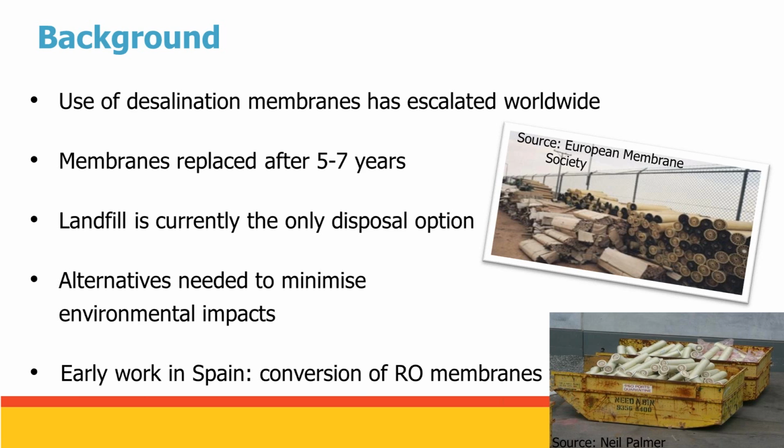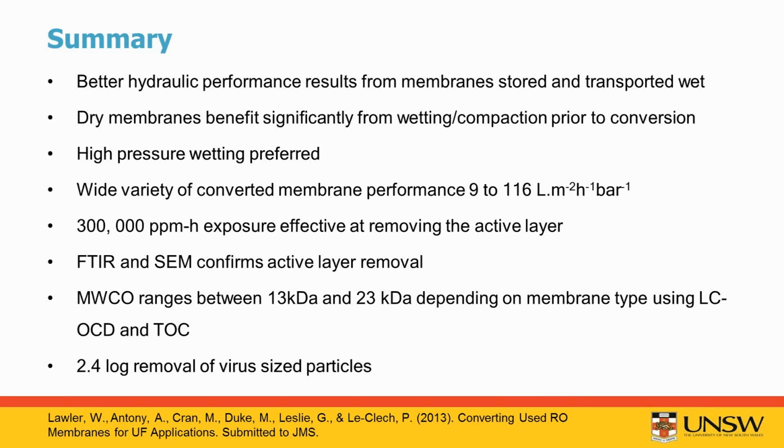And of course, now you're probably thinking, what sort of applications can we use this for? Using the test that we've shown, we say that we can use this potentially for pre-treatment for seawater RO, tertiary wastewater. Some of the more traditional applications for UF flat sheet membranes are a little bit outside the range, including pharmaceutical and food, because of the obvious strict requirements for integrity and hygiene that are required in those industries.